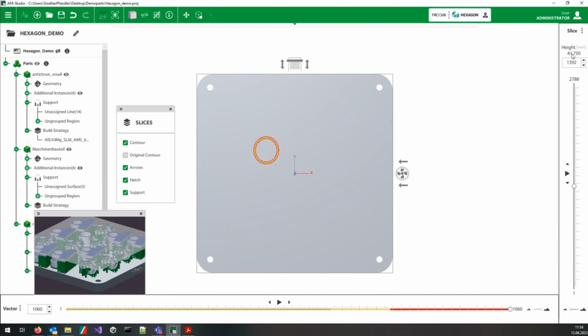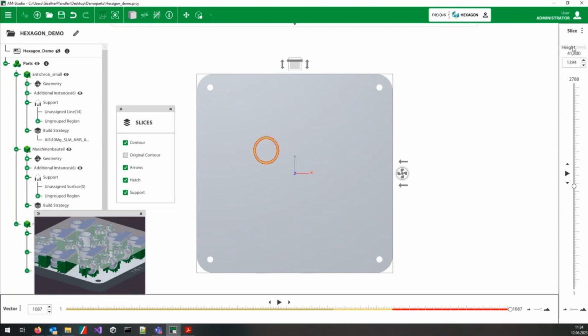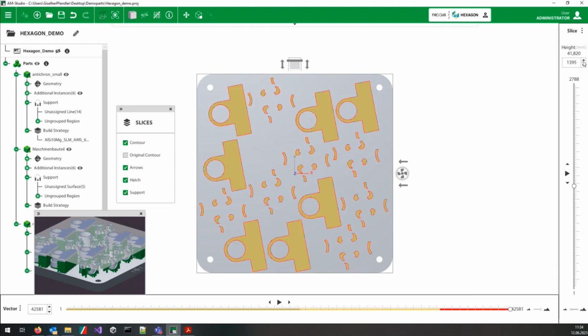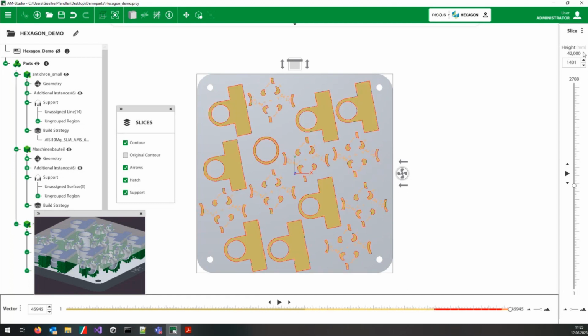So now we are on 750, and now on 760. There are only 10 microns between, so that's not good. Now we have 40 microns, as we are on the 41.8 with this one again, and then the 20. So these parts are moving in 60 micron steps and the others in 50 micron steps, and that's why this is not working that well. But now the next one, here we have all again, because it's the fifth. Every fifth time we have all together in one slice. I don't know whether it's clear or not. Sorry for going too much into detail.